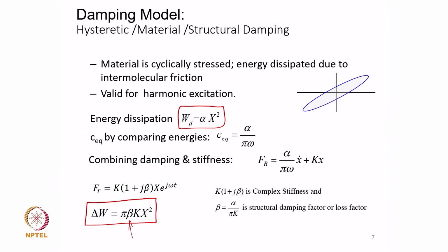So, the second type of common damping model that we have considered here is the structural damping model. We shall take some examples based on this little later, but let us now very briefly look at what is the third most common damping model. Now, obviously, if it is not a viscous damping, if it is not a hysteretic damping, you have an alternate damping, that is the third type of damping, which is called the Coulomb damping or a dry friction damping. But I think before we do that,